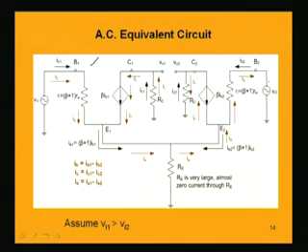Similarly, the unbalanced collector current IC is equal to IC1 minus IC2. Similarly, IE is equal to IE1 minus IE2, and the directions of these unbalanced currents are shown by the red arrows. IB flows in this direction, IC flows in this direction, and they meet at the emitter point. The total emitter current IE equals IB plus IC, flowing in this direction, where one part is IB and the other part is IC. So we are denoting the final unbalanced currents by the red line.